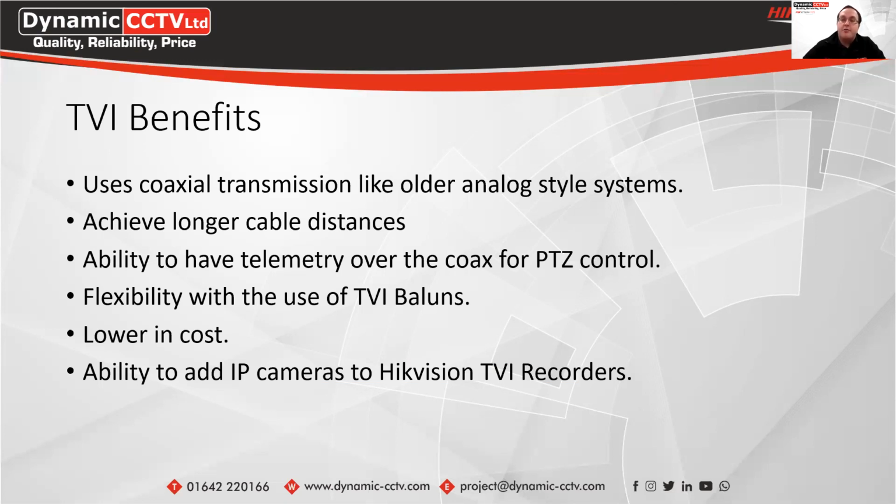So instead of having to run your own telemetry cable, it'll actually send the telemetry down the same coaxial cable, or Cat5 if you're using balun, down the same cable as the actual video signal. So it does save on that extra cabling infrastructure needed for legacy systems.